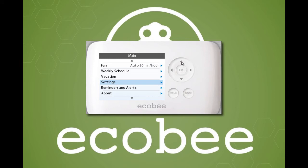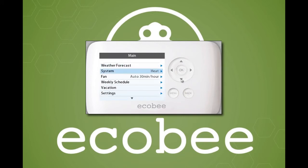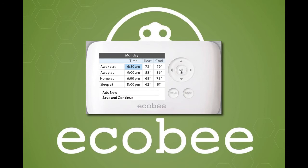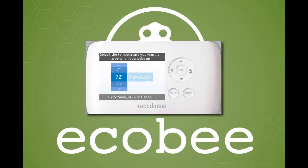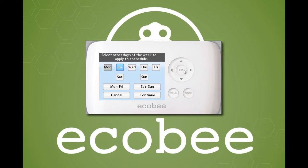Once you have a setting option highlighted blue, press OK or right arrow to access this option. To set up a 7-day program, press OK to edit the default schedule. Start with the day of the week that you want to modify. Typically that would be Monday. Using the navigation buttons, select the times for both heating and cooling set points and status for the fan for each climate period. Once you're satisfied with these, then move down to the Save and Continue and select the other days of the week that you want to be the same, then continue.